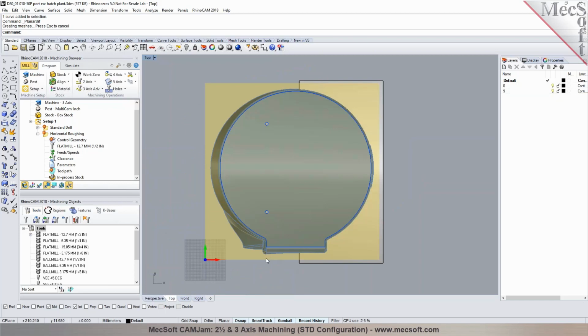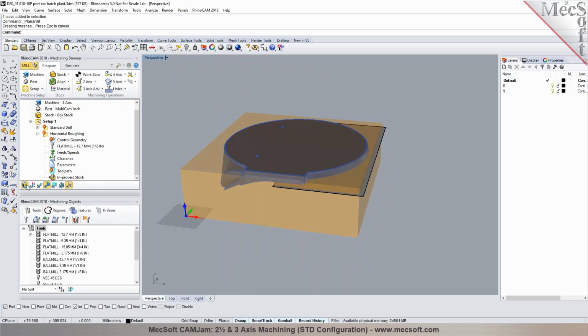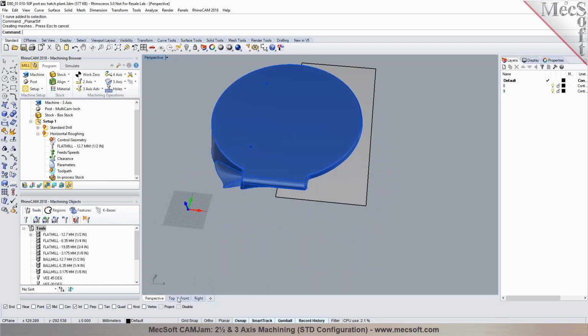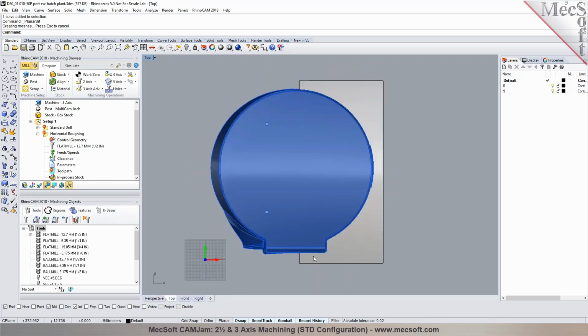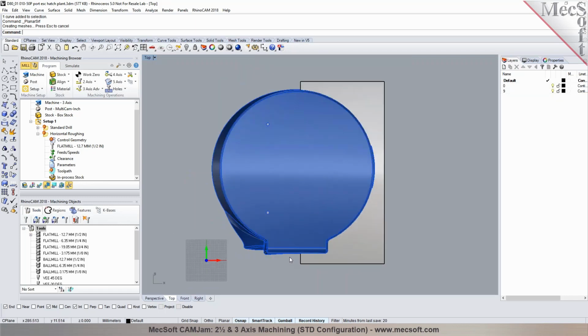Maybe you can have one over here depending on what areas you don't want it to cut. You can put in areas that you... So do you make that plane as a boundary, or how does that work in RhinoCam? If you take a look at this, if you look below the plane, you can't cut anything into it because that's like an undercut. RhinoCam will not be able to machine anything that's below the plane, and since the stock is over here, it's not going to go past that area.